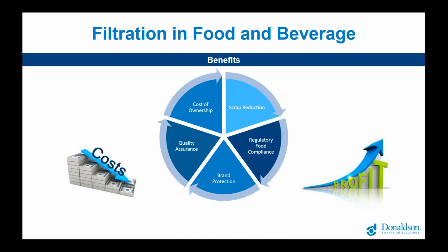So there's an ASTM test that is available that shows that the filter must pass a test. It's a pretty rigorous test. It has to be able to retain at least 10 million bacterial cells before one of them can get downstream. And that's per square centimeter of filter media surface area. And there can be hundreds of square centimeters. So that would be the test that qualifies a filter as a bacterial retentive filter or a sterilizing filter.